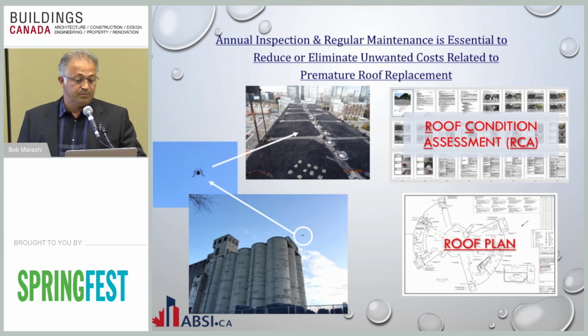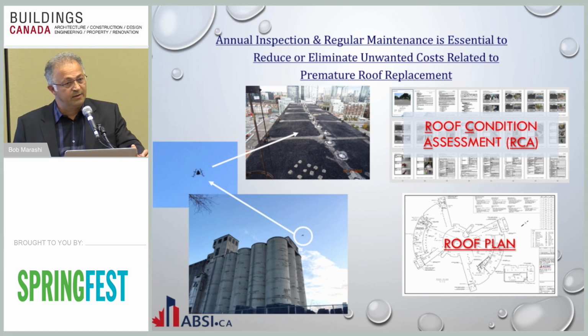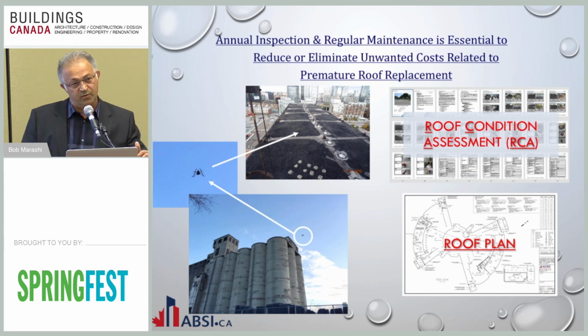It is very important to perform annual inspections on a regular basis for roofs. It's usually recommended twice a year, before spring and before fall. And when you do that, please make sure that you get a report with it and a drawing that indicates what the problems are. Keep that information on record. Keep a good log over the years. As the building ages, I've seen that one engineer comes, another goes, another engineer comes, another goes, and nobody knows who and what they did before.